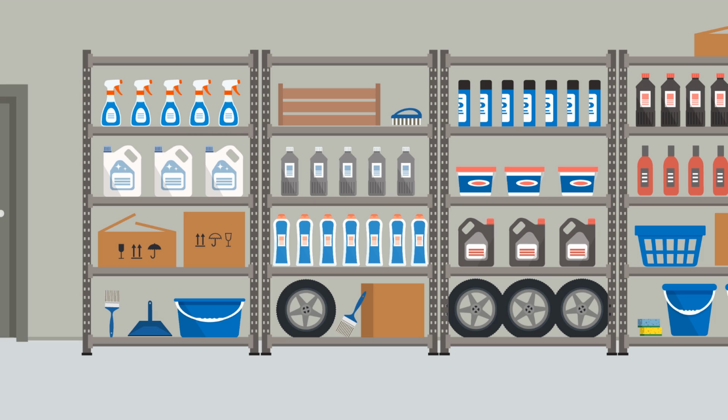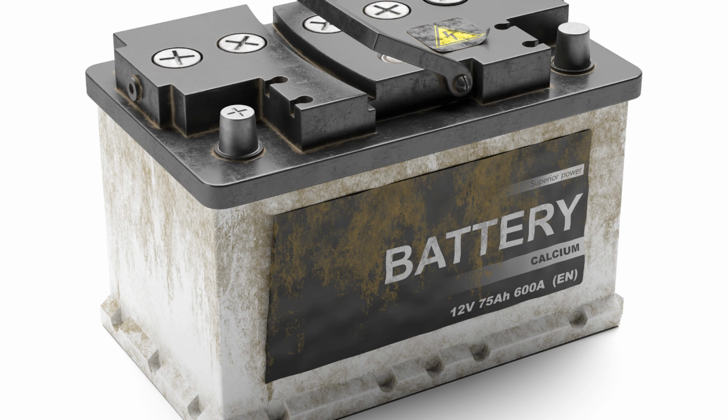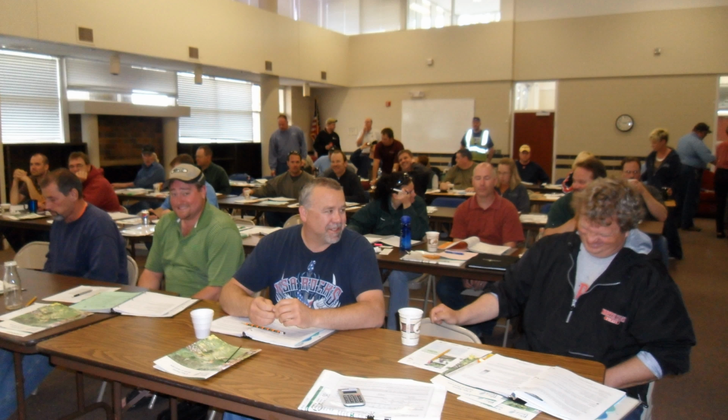Whenever possible, keep chemicals stored off the floor and indoors. Store materials away from high traffic areas. And store batteries on open racks. Return used batteries promptly. And contain cracked batteries to prevent spills. And most importantly, you should have regularly scheduled trainings for employees in spill response procedures.